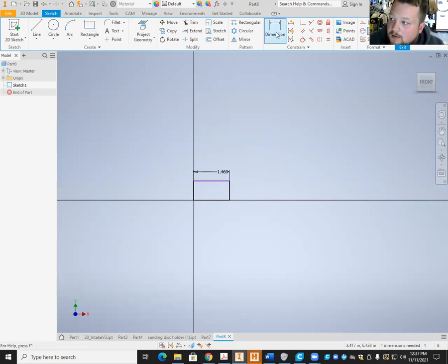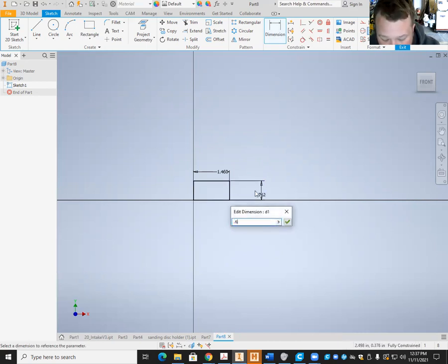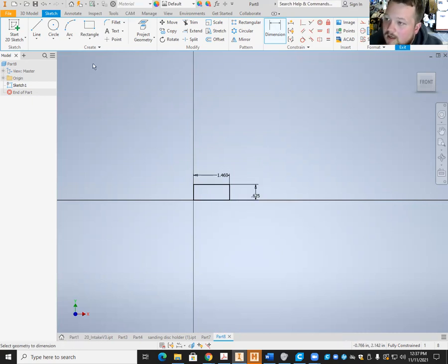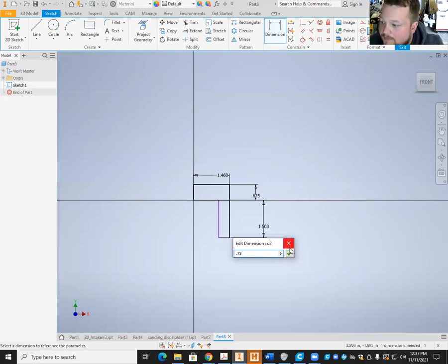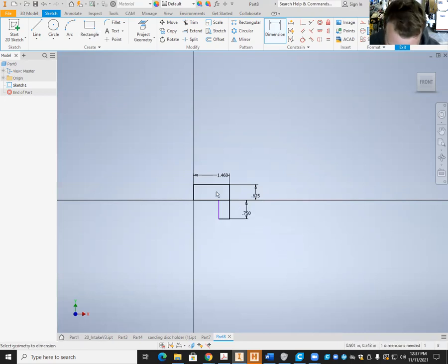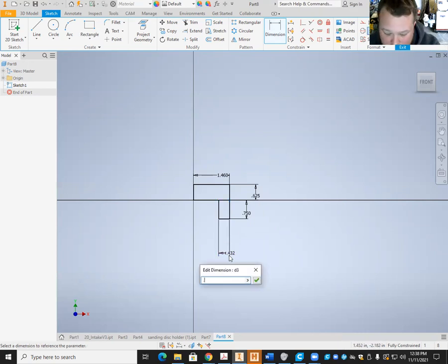And the depth of this part, we're going to go with 0.625. That's 5/8 of an inch. There's also a little thing that sticks off the bottom here, kind of like this. And we're going to make this guy come off 0.75. Okay, now we're ready to extrude this shape. You can see this line is not dimensioned, and that's definitely something we should do. I kind of was forgetting about that, I'm not going to lie. Looks like this is 1/4 of an inch thick, 2.5.